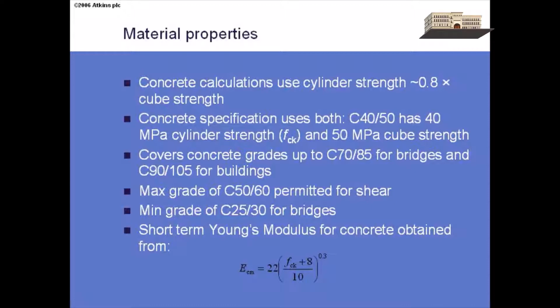Very specific points, but in terms of the E value, in BS 5400 there's a table. In the Eurocode there is a table, but in most situations there's a formula. All the Eurocode has been written around trying to eliminate the need to look things up in graphs and tables. And I think they've done that everywhere, so there will always be a formula for something like that. And the value for Young's modulus for concrete, the mean value, is a function of fck, the characteristic cylinder strength.